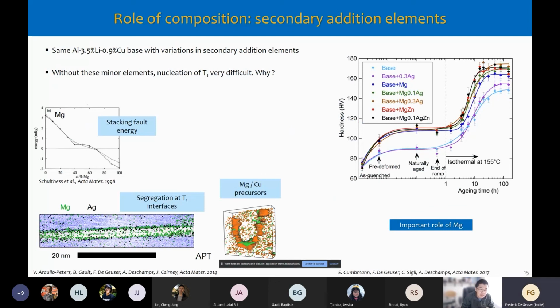But in fact, I actually probably deleted a slide by error, which is supposed to be behind this one. But the general idea is that by TEM, these precursors we've observed by atom probe. So what you see here in orange is a magnesium isosurface, and you see that it's sort of curled around an object which is likely to be a dislocation.